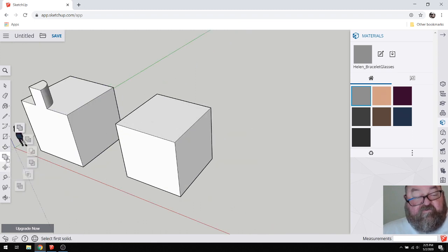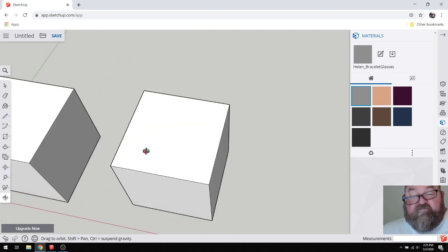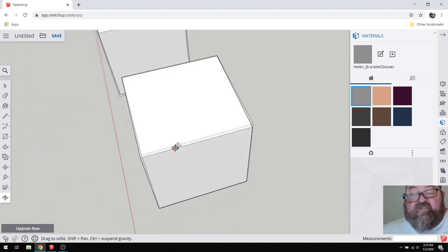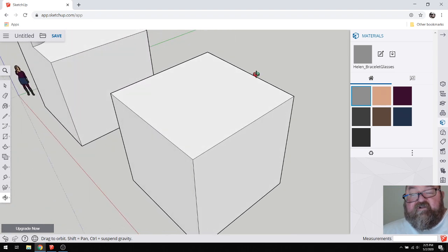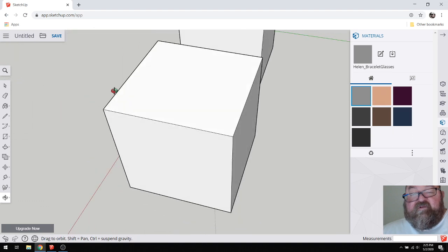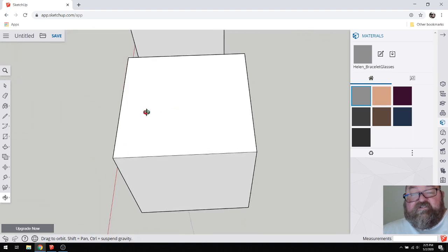We've used the move tool, and now we're going to use the tape measure tool, which is most commonly used as a construction line tool. This is a good time to build a little roof, even though it's going to be a cartoon looking roof, it will still be a roof. Let's say we wanted to find the center of this block, and we took our tape measure tool.